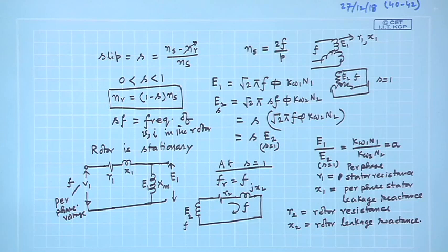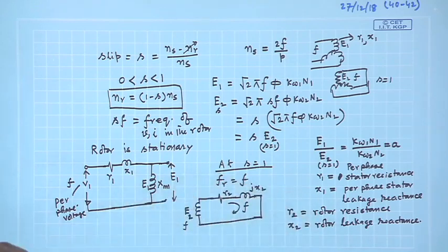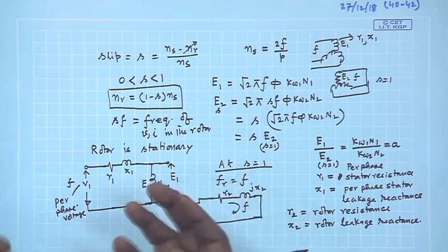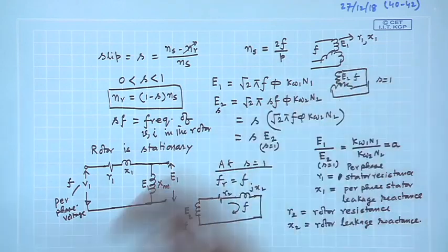Therefore, in whichever circuit L is present, its reactance omega L depends upon the frequency. For a given supply, to analyze the circuit, the frequency is fixed everywhere. Therefore, whatever X value you show in the circuit, that is omega into L, and omega is fixed. Now, here is a different situation in the case of the induction motor rotor coil.